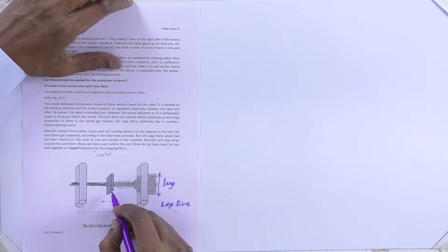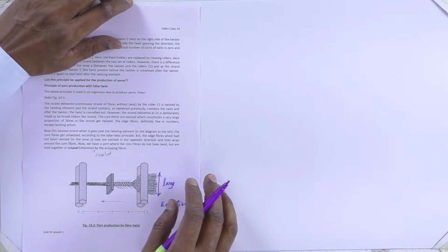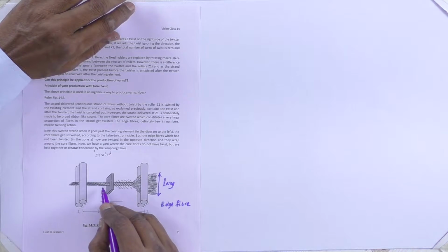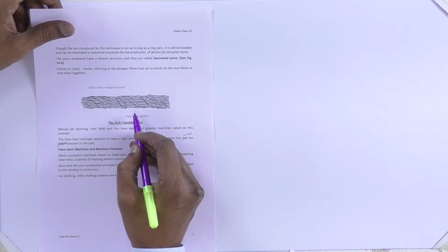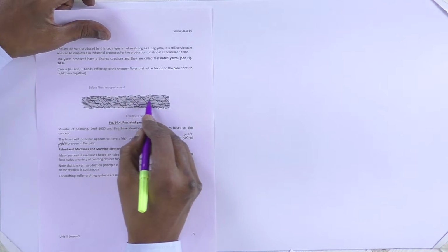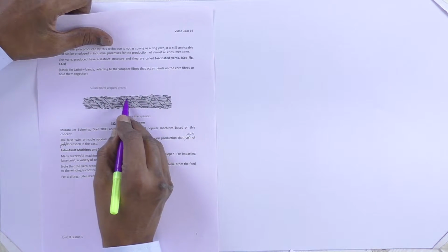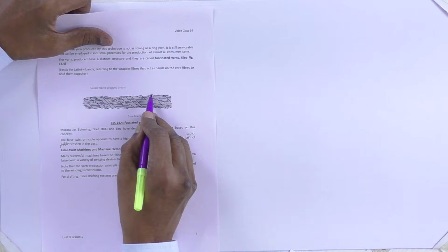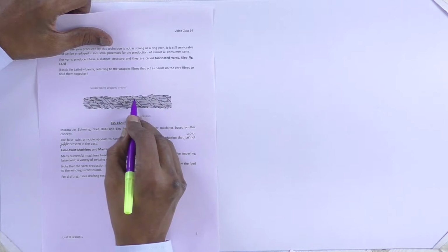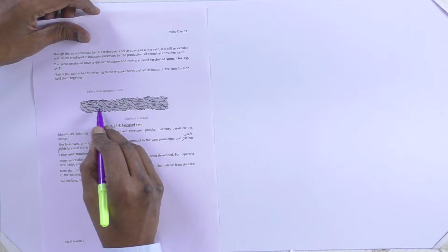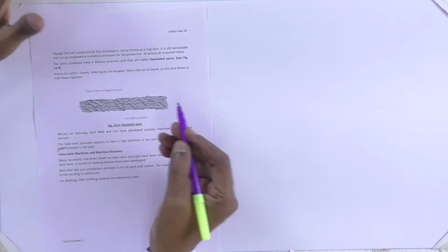You can see here only a very small amount of fibers, to the extent of 5 to 10%. They hold the core very tightly. So the yarn produced looks like what has been shown here. You can see these parallel lines, these are the core fibers, and you can see these are the wrapper fibers, and these wrapper fibers provide the stability to the structure. If all fibers are parallel to each other, there will not be any coherent structure.